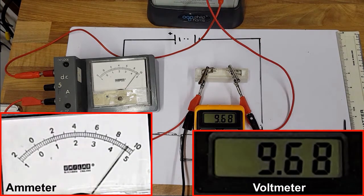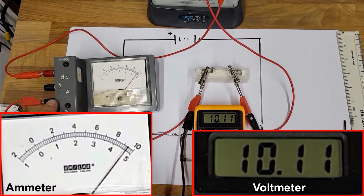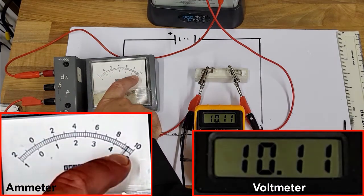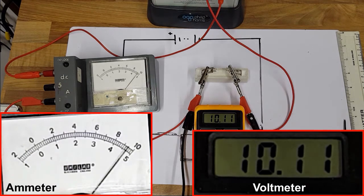So on the voltmeter, you can see that we have a potential difference of about 9.5, just a little bit over. And over here, we have a current, if you remember this is from 0 to 1, so this will be a current of around about 0.95-ish. Okay, so that's where we're at. So the potential difference is jutting about a little bit, probably due to some internal fault with the wiring, but nevertheless, around about 10 volts is around about 1 amp on this.